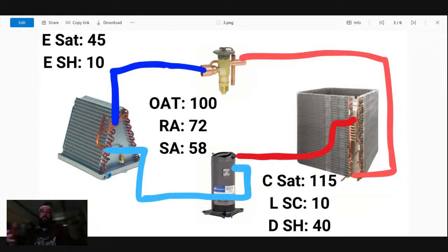It just is running different than it was. Most of the time we rarely get feedback any better than that. So do we see TXV overfeeding? TXV overfeeding because of a bulb issue, because our superheat is maintaining okay, I would say more than likely not.